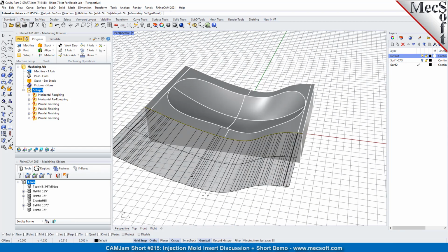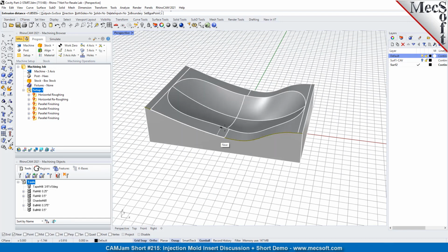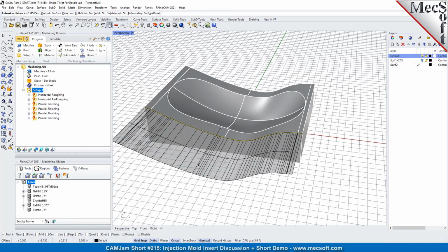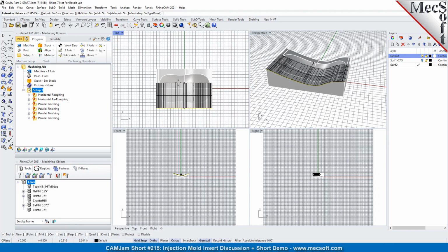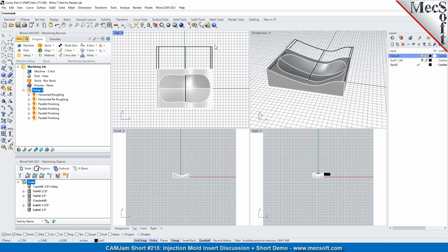We're going to right click, and you'll see that it's extruding in the default direction of the parting surface. We don't need to know exactly how far it's going to overlap. We just need to make sure that it's at least half of the tool radius. So we're going to bring it over a little excess.